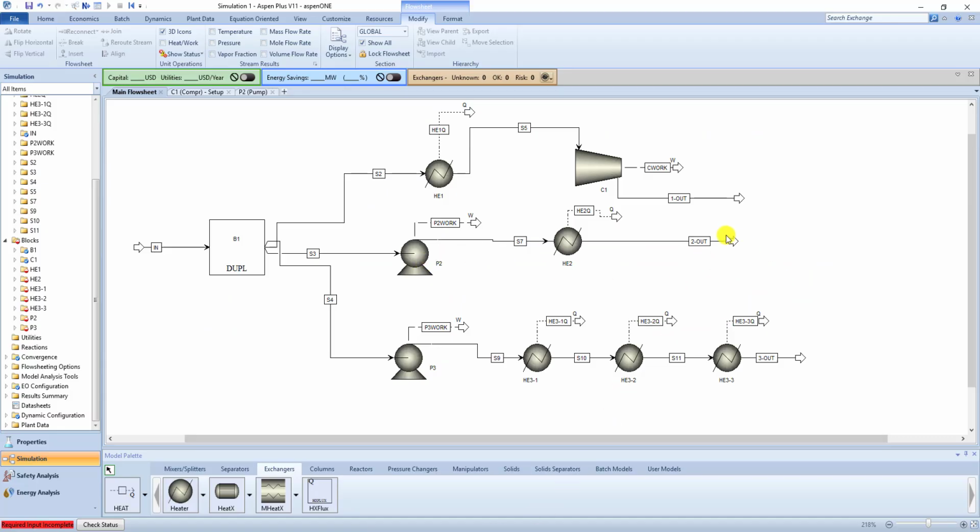So for pump 2, if our outlet is 75 psi, then if we have a 5 psi drop through our heat exchanger, which is fairly customary using heuristics, we can then say that our discharge pressure is 80 psi for pump 2.